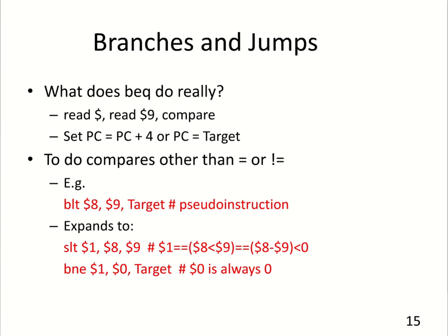One thing that you should be aware of is that in the MIPS instruction set, when you refer to register 0, instead of there being an actual physical register that can contain an arbitrary value, register 0 is always hardwired to 0. So it's a shorthand way of specifying an immediate value of 0 for these kinds of comparisons. But one of the restrictions that creates is that you can't store any temporary values, or assign any variables, to register 0 either.